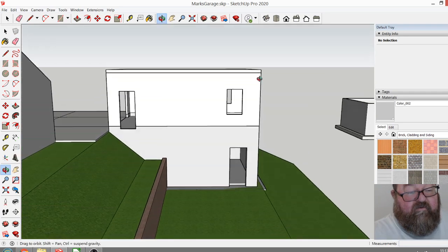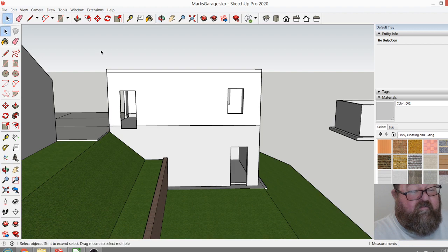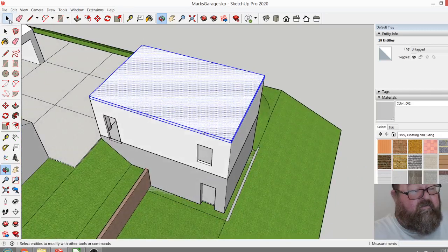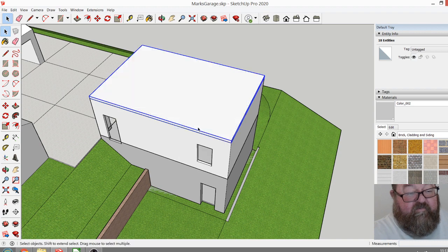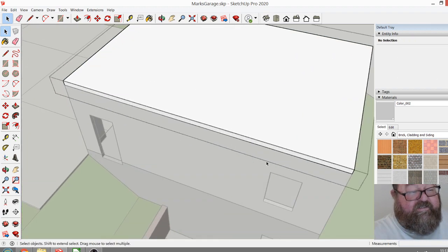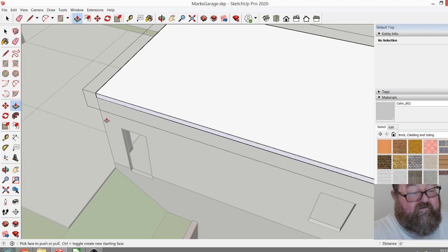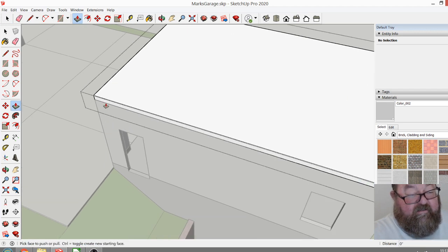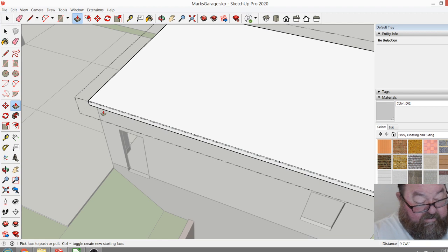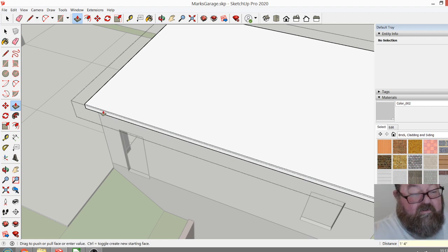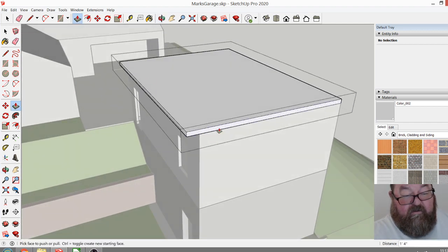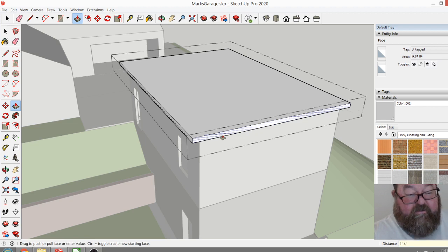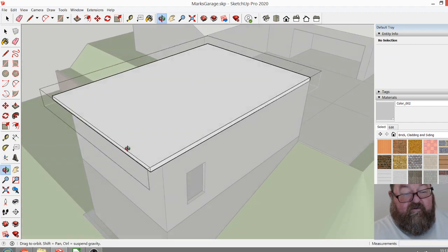And then I'm going to make another group. We'll make my roof a group. Speak Italian while I'm drawing. Group. And this is an easy way just to draw a graphic roof, just a graphic representation. I like 2-foot overhangs, but this is kind of a small building, so I'm going to show it as 16-inch, which is pretty common.